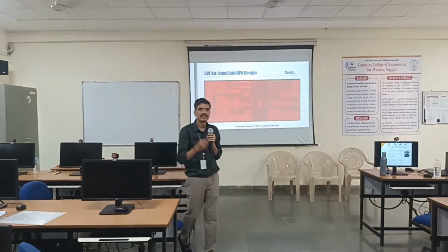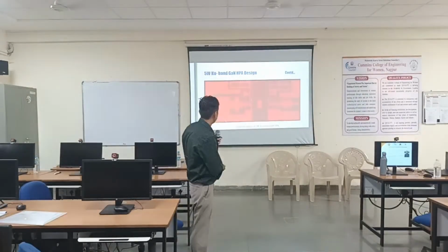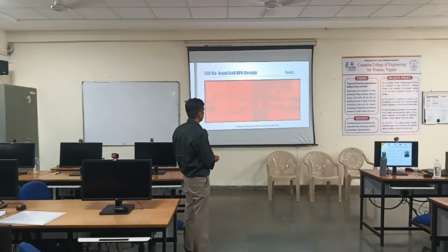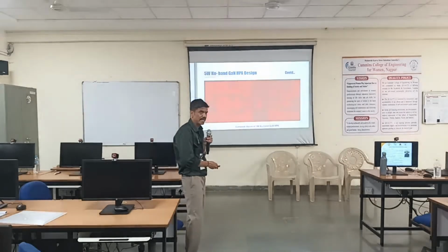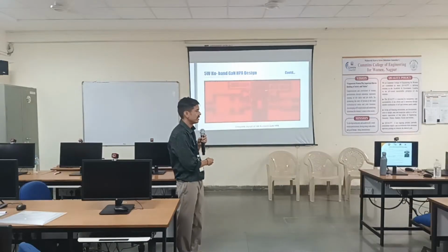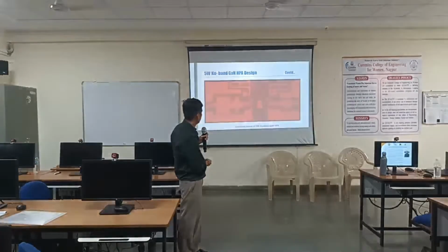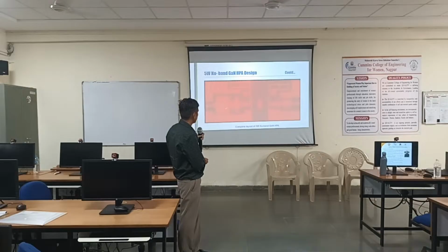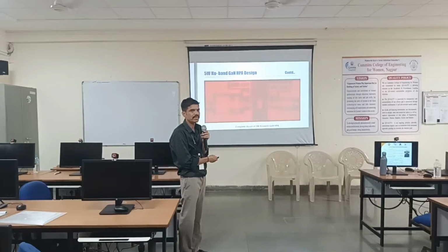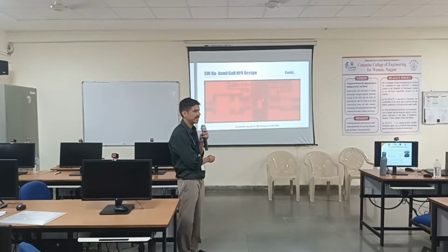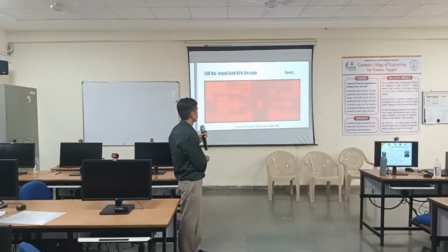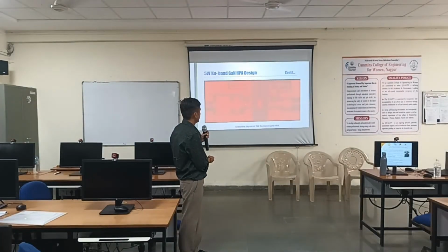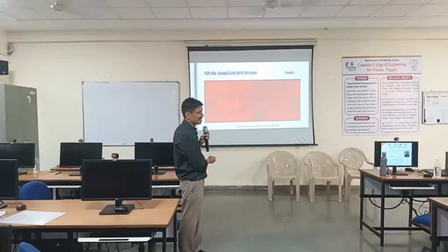This is the layout. Somebody was asking, this is the actual layout. Here my transistor will sit. This is the bias network. Then something you can see here. What is that? That is radial stuff. If somebody is interested, I will say something on that. Otherwise, I have to move to the tool also. I have placed some tuning pads. Once it is fabricated, if something is not working as per expectations, I can change the width. For those purposes, these tuning pads are being kept. This part I have not discussed anything. That is for stability improvement.